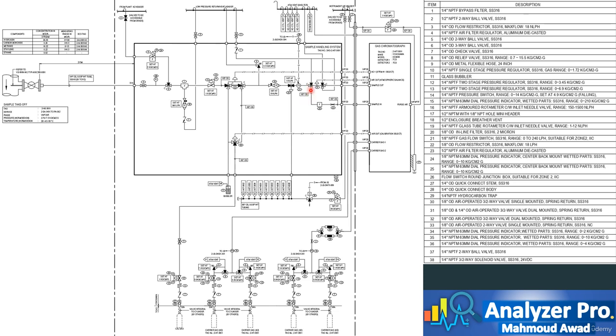That is the function of the atmospheric valve. When actuated, the valve blocks the gas chromatograph sample inlet port and depressurizes the sample that is already inside the gas chromatograph to the atmospheric pressure through the gas chromatograph outlet port.